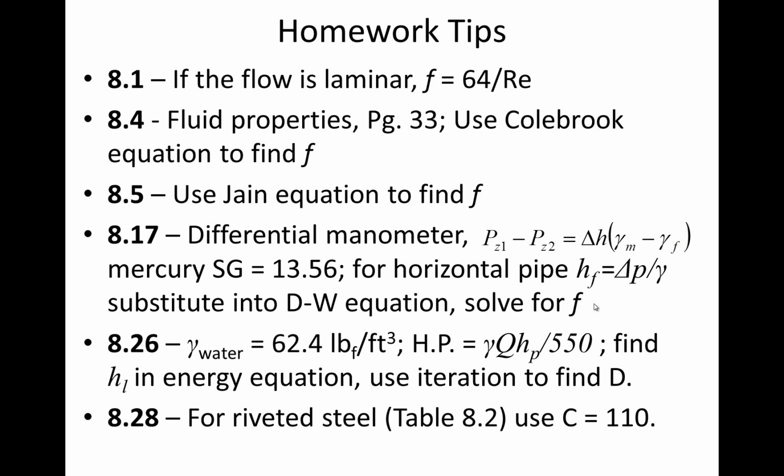In problem 8.26, I wanted to remind you that the unit weight of water is going to be in terms of pounds force per cubic foot. The units are a little bit strange when you start working in British gravitational units. You can calculate horsepower, HP, by the unit weight of the fluid, in this case water, times the flow rate, which has to be in cubic feet per second. So I think you'll need to make a conversion in that problem from the given flow rate into cubic feet per second, multiplied by the pump head.